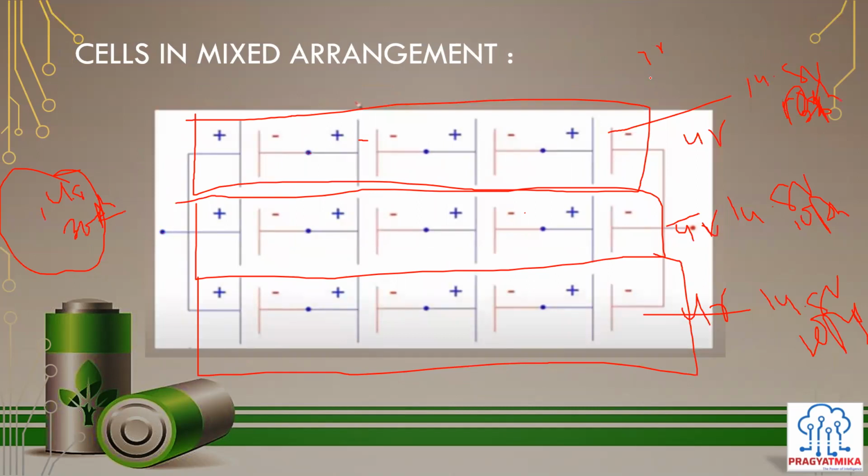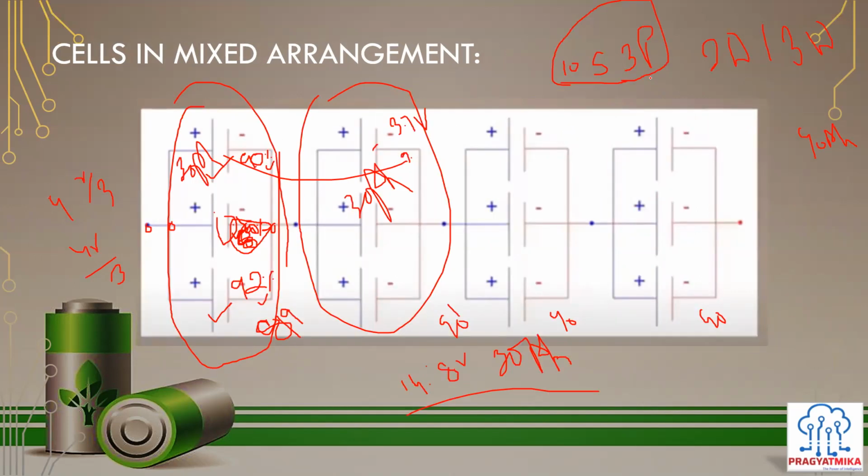Yeah. So the BMS available is like 10S, 12S, 14S, 18S, such kind. A BMS is not available for 30S series or maybe 100S series. If you have to use such a BMS, then a master-slave BMS is used, where multiple slave BMSs are connected to a master, and then they are used for our application, and the application becomes quite expensive in that case.